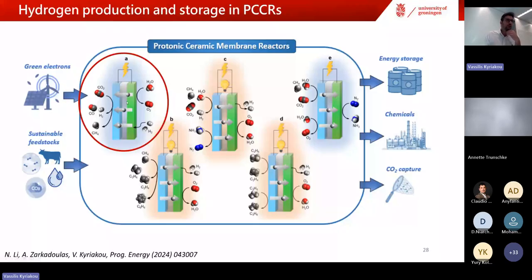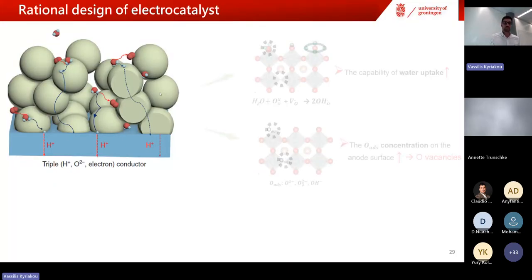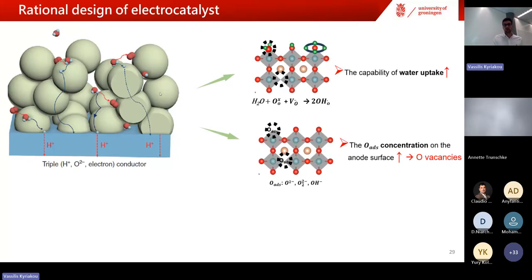However, the problem that we mainly have, except for the catalyst at the cathode that I'm not going to touch today, is the water splitting. Here, the environment is different, and the reaction is much more complex. So in traditional solid oxides, your water splitting takes place at the cathode. In this case, the water splitting takes place at the anode. So you have to oxidize the steam into protons and oxygen that evolves from the electrode. If you want to do that at high temperature, you cannot use metals. So you have to go to perovskites as well, or at least some other type of mixed conductors.